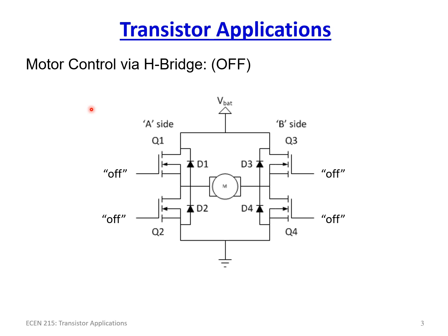One of the ways motors are controlled, especially DC motors, is through something known as an H bridge. Sometimes it's a little hard to see. If you're working with an electrical engineer on a control system, you're probably going to hear them say, we need to put an H bridge in the system. All that's referring to is basically a way of delivering current to a motor or a load, in this case a motor, in a way such that I can change the polarity.